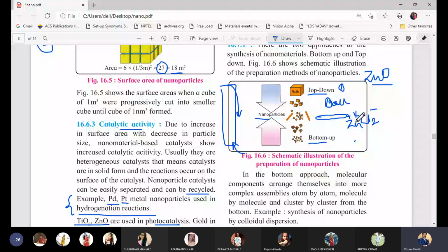Then if you take this gel and rapidly dry it, rapidly dry means you take it out from the oven and put it into the fridge, an aerogel is formed. In an aerogel, the gel remains a gel, but certain air pockets form inside it, that is known as an aerogel. Rapid केलं तर drying. If we do a normal type of drying, a xerogel is formed. Xerogel means no air gap will remain here. This is highly appreciated if you get a xerogel.